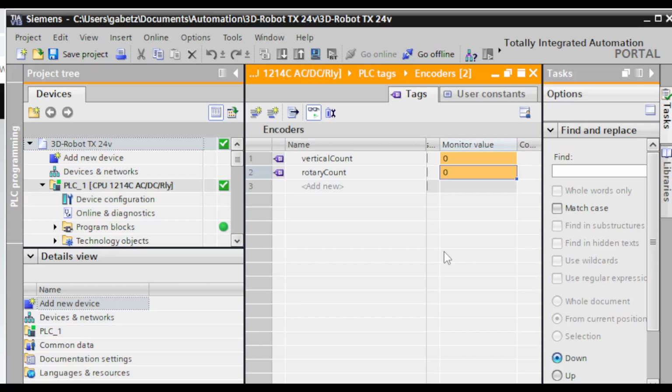All right. So, high-speed counters. They're not complicated to get set up. To me, the most annoying part is the direction. And as I said, right now, I don't have a solution for flipping the direction. The things I've tried in the past using the high-speed counter function block control haven't worked.